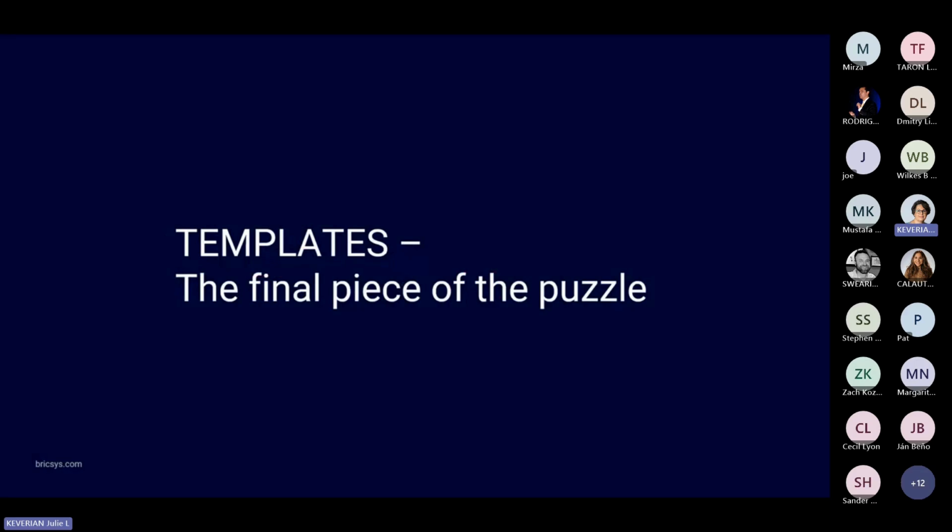So we've built block libraries. We've started to organize our content. We're following best practices for maintaining those default standard styles. And we've got our standards library set up and accessible through the Drawing Explorer folders. What else do we need to do? We need to look at our templates. Templates are another key to making your standards reusable and consistent across projects. And it's really easy to create a template. So let's take a look.